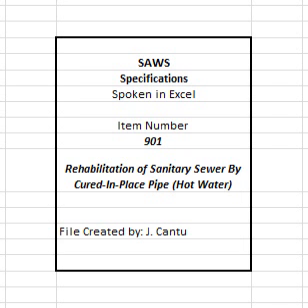F. Temperature gauges shall be placed between the impregnated tube and the existing pipe at the invert level of each end to monitor the temperatures during the cure cycle. A written log shall be kept and submitted to the owner. Any invalid temperature readings not recommended from the manufacturer will be cause for rejection.